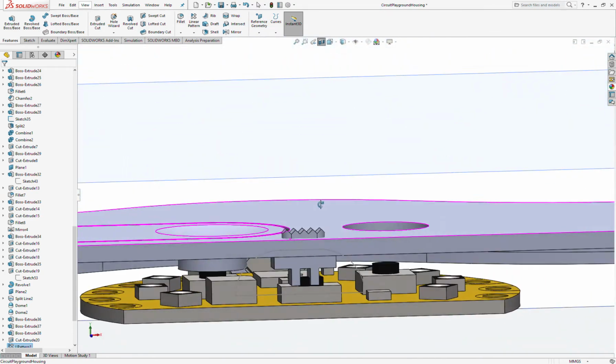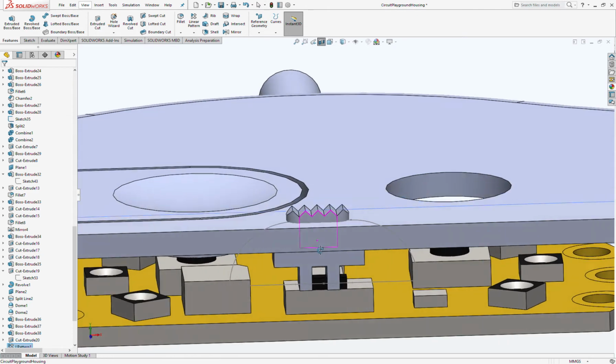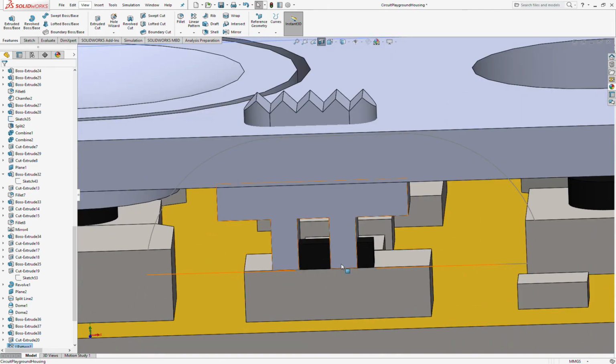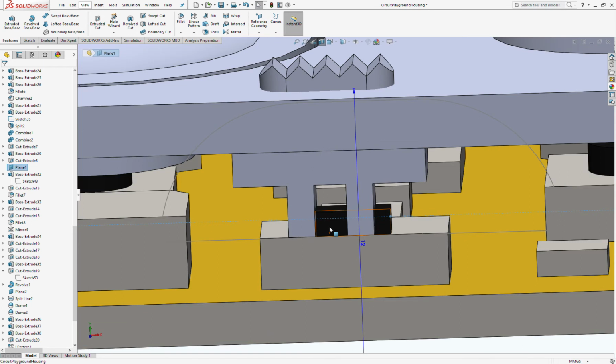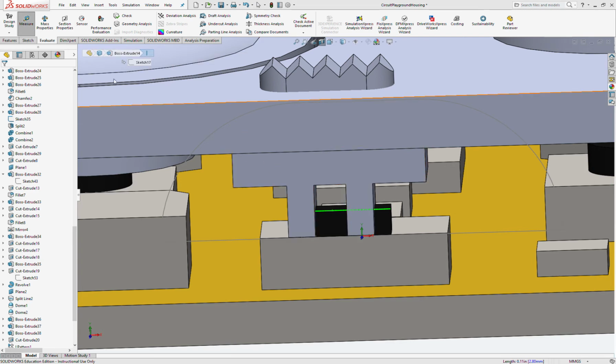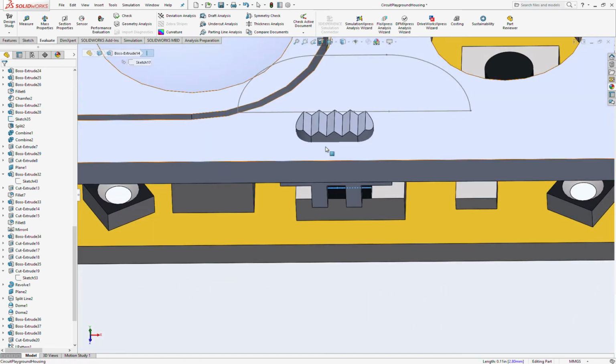So now it's sort of the hard part, if you can call it a hard part, of the switch. It's just knowing how much throw the switch has. You would probably want to measure this as well, but we can make a reasonable guesstimate by using the measure tool. That edge there is 2.8 millimeters. So from this edge, maybe till there or so is where that face of that button is going to go. So maybe 2 millimeters or so.